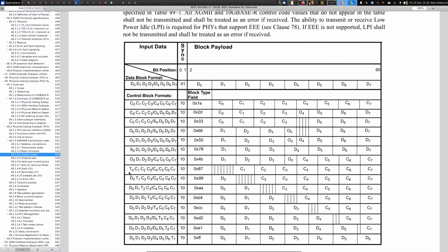So there's something that I've used before called COBS, and with that, what you can do is it basically removes all the 0 bytes. It encodes the data that you're sending so it has no 0 bytes in it, and then you can use 0 bytes for framing. So, there's a few things you can do by layering some stuff on top of something like a normal serial link.